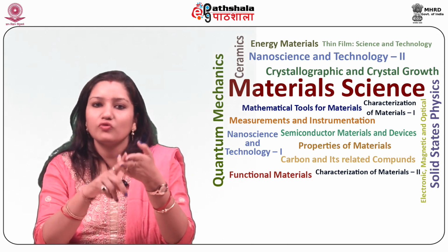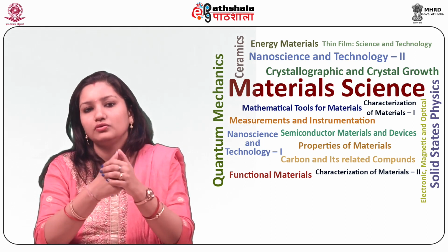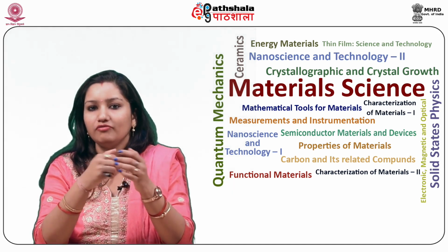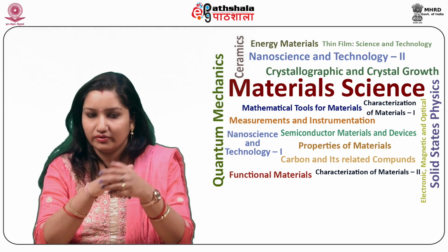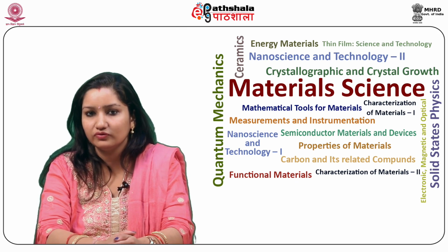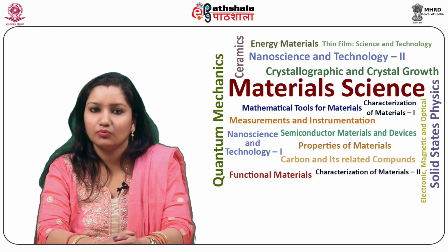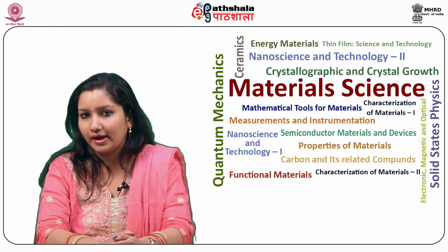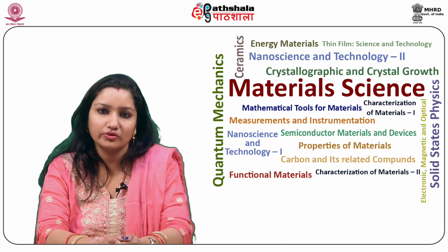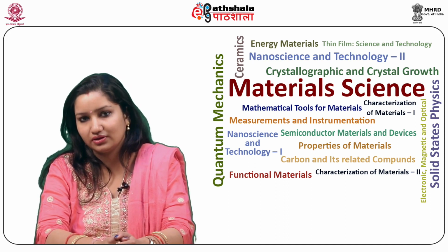Secondly, low space efficiency. We generally need to cover a larger surface to output the same electrical power as we would get with a solar panel made of monocrystalline silicon. However, this does not mean every monocrystalline solar panel performs better than those based on polycrystalline silicon. Monocrystalline and thin film solar panels tend to be more aesthetically pleasing since they have a more uniform look compared to the speckled blue color of polycrystalline silicon.